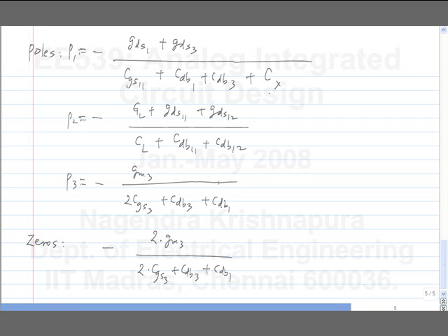Or I can do it to this one. Okay? I can do it to one of these two. Right? I can always make P2 much smaller than P1 also by hanging a large enough capacitor. But is that what I want to do? What's the problem with this? So it will compensate it, no doubt. You can make it stable. You can make any circuit stable by hanging a large enough capacitor from some particular node. Okay? But what is the unity gain frequency you will get? That's the problem. Okay? You will reduce the bandwidth to very low values.